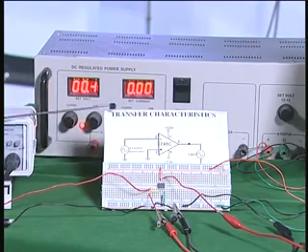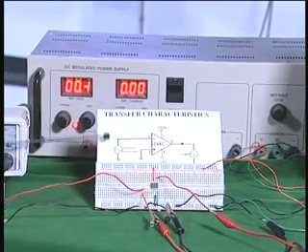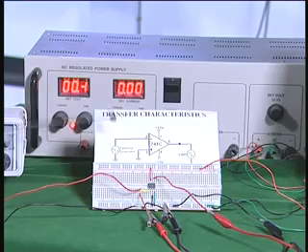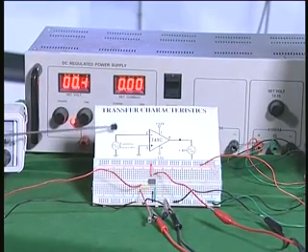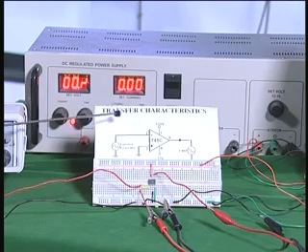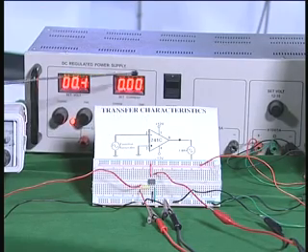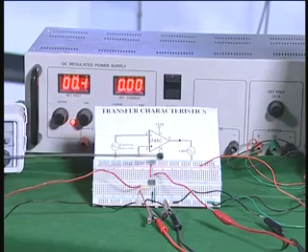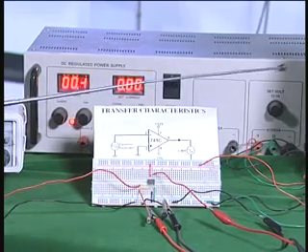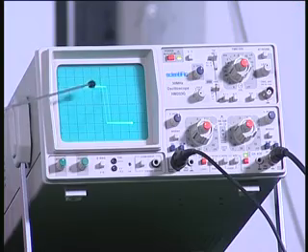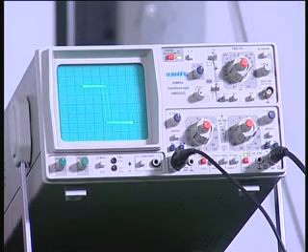Every time it goes up and down, it will certainly cross that 120 microvolt approximately, that I mentioned. Therefore beyond that 120 microvolt the output will become saturated at plus 12 volts or minus 12 volts as the case may be. What you see behind is actually the dual supply which is connected to the breadboard. So you can see on the oscilloscope screen the picture which I showed you just now.